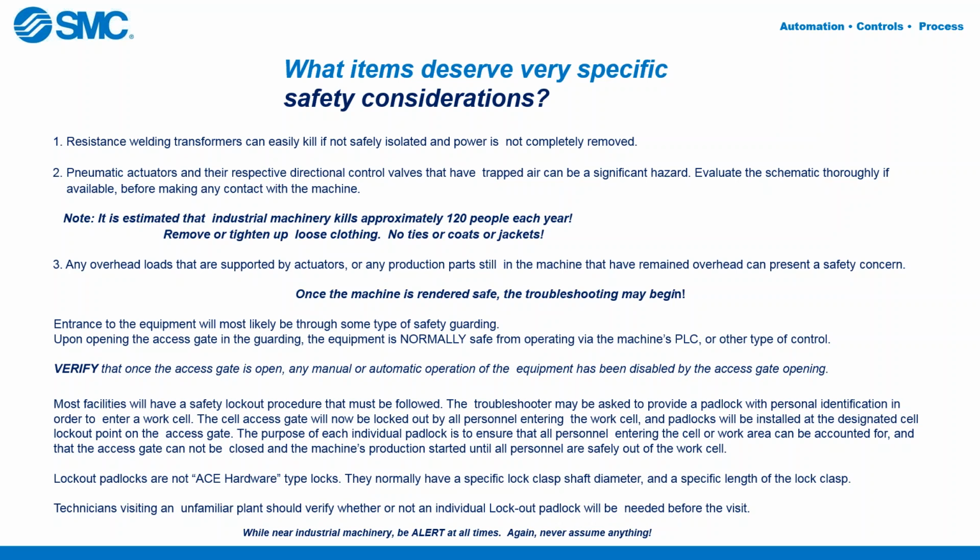Also, something to note here is where the lockout tagout is. If it's in full view of all the moving parts of the machine, that's certainly easier and safer. If the lockout device is such that it's possible for the last person to remove their tag and not have noticed that someone else stepped into the danger zone, you want to make sure that you're considering those sorts of scenarios as well. If there's any chance that someone could have entered the machine while you were occupied with a lock, you want to make sure that before anything's started up that there's a final check that's done.